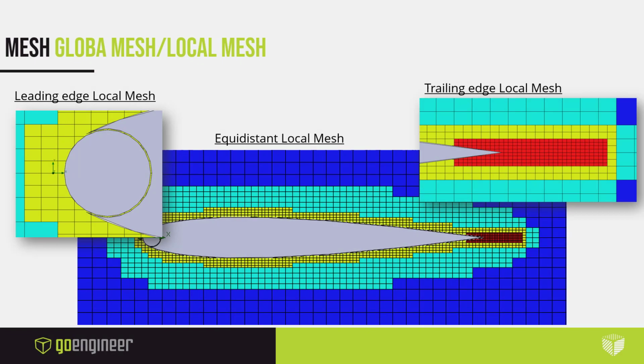And what that looks like would be here. So these are going to be the smaller ones. This is only 2 levels, not 3. But this would be, in this case, the 2.2 millimeters, and then this would be the 5 millimeters, and then this blue area could be the 10 millimeter in height. And then I wanted to suppress these again when I run the parametric study. That way I can look for a trend in the parametric study.